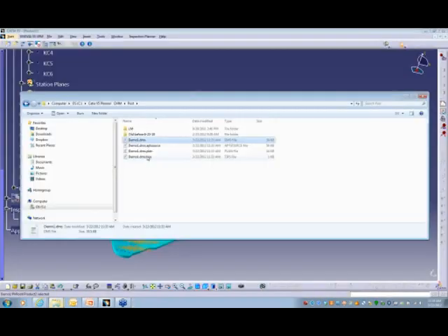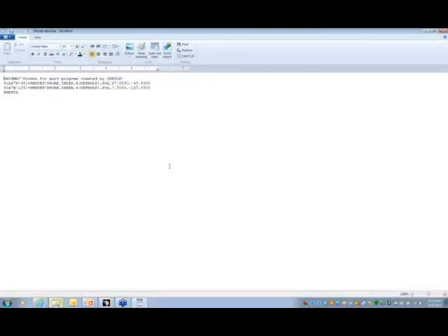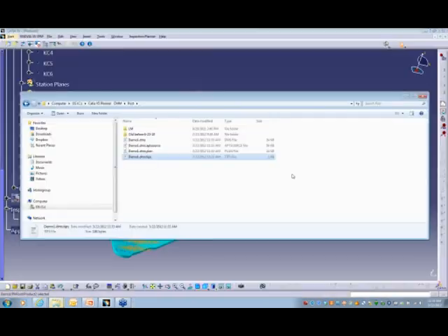And then depending on the different CMM software, Virtual DMIS likes to have an external tip file. So these are the probe angles that were created. I can open this in Virtual DMIS and hit execute. They automatically calibrate. In PC-DMIS, these angles are kept at the top of the DMIS statement. When you open up the DMIS, it'll say these probes are not calibrated. You want to calibrate them at this time. You say yes, and they go calibrate. So depending on the post processor, the tip files are in a different location.